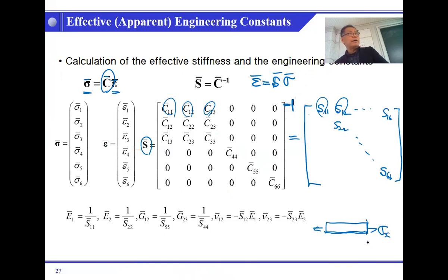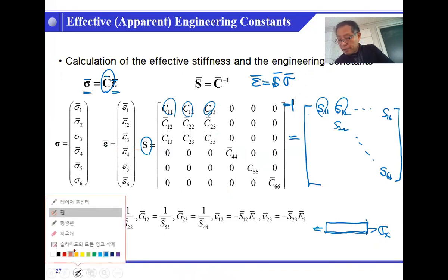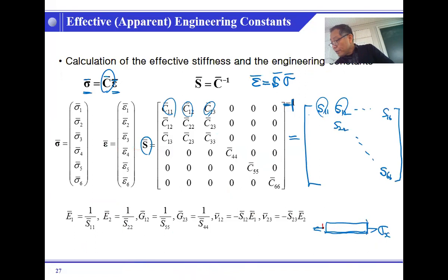And then we measure the deformation: extension in the loading direction, and contraction, which is a very important point, epsilon y, and also the thickness contraction, epsilon z.